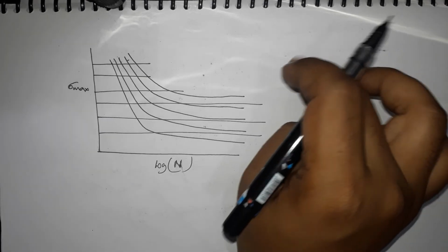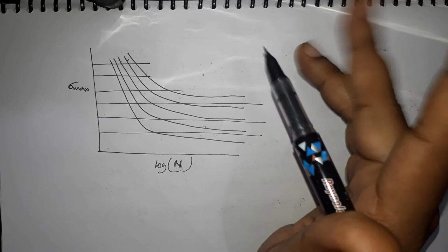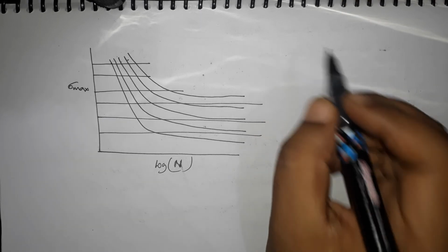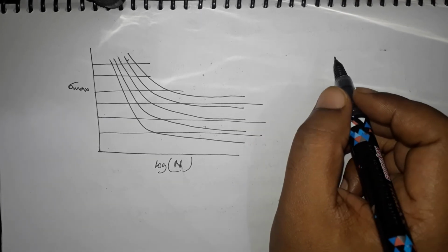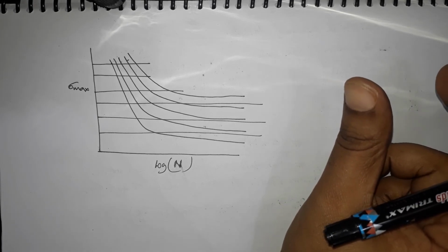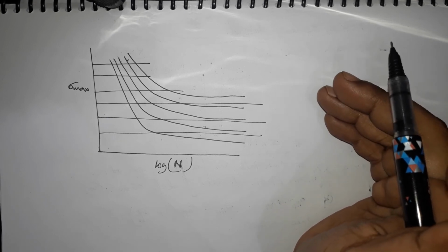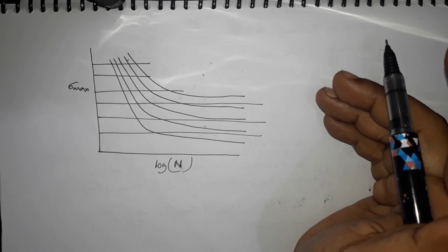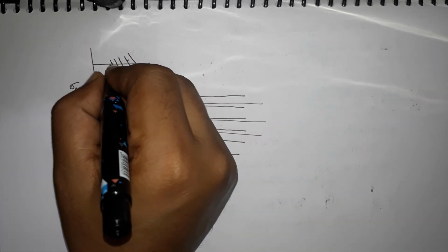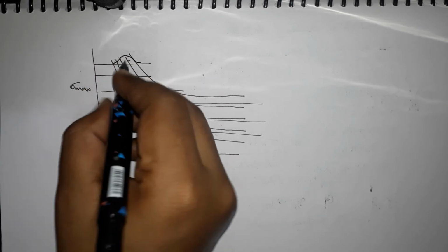So it's the same thing, but 5 people will be taking different options depending upon their comfort and a lot of other things. Similarly, each specimen will act as its own entity and they will deal with the cyclic loading in their own way, because they have different amounts of defects in it and they will fail at different numbers of cycles. So what you have is a probability distribution at every point.